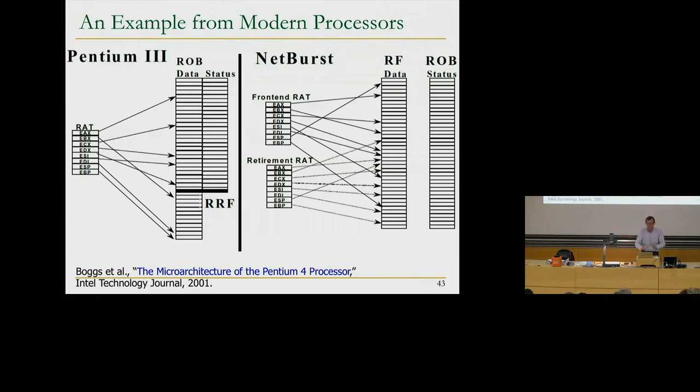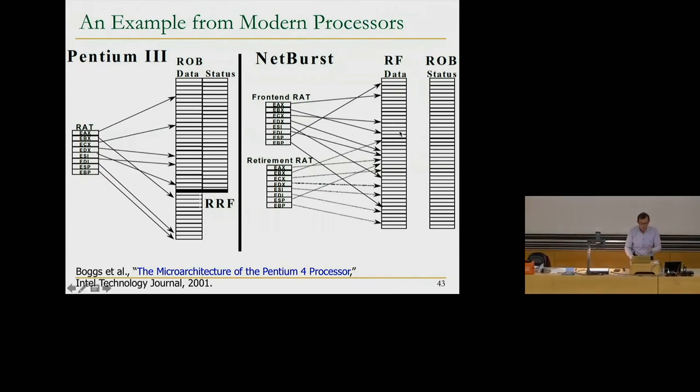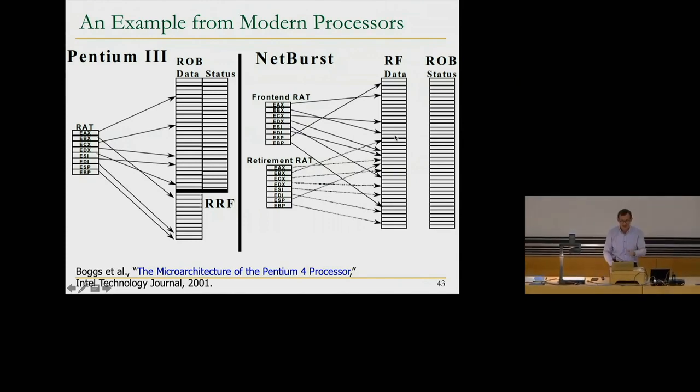They're all consolidated here, and whenever you need to access a value, you basically use the physical register ID that you're waiting for, index the physical register file, and get that value. Whenever you need to update a value, you send the value to the destination physical register that you're writing to, and that gets updated in the register file. So that's beautiful. Nothing stores values other than the register file at this point, at least register values.